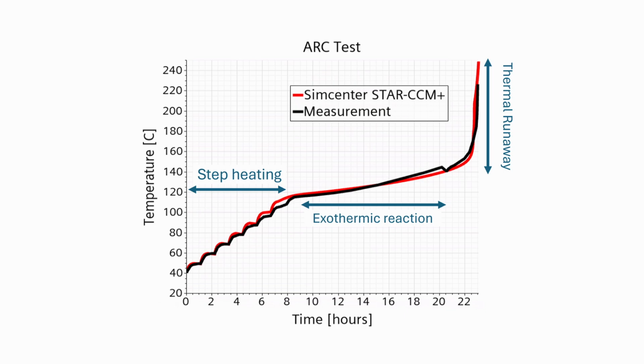So with this ability to do detailed cell level thermal runaway, you can understand how the battery behaves and maybe how it will behave inside a wider pack. You could use this as a means to generate heat release that you could put into a pack level model. And then you can really design a safe battery system that can either withstand or completely avoid the onset of a thermal runaway situation. Kind of similar to the previous feature that I just talked about.